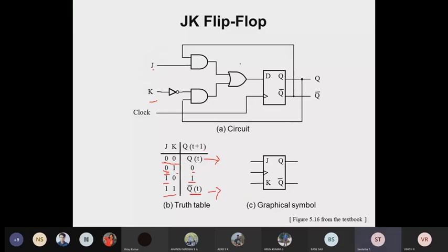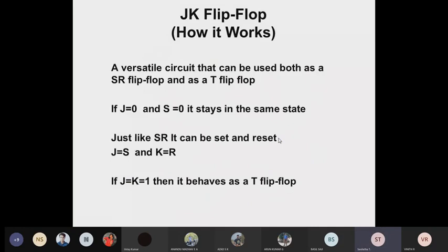So whatever the value we have at this juncture, that's what you're going to receive in the case of the JK flip-flop. Again, I'm going to use positive edge triggering. The positive edge triggered will provide you the output value. It will sync the value during the emergence of the clock edge at this location, right? So this is how the JK flip-flop will look. Once you observe the timing diagram, you may see the information clearly.